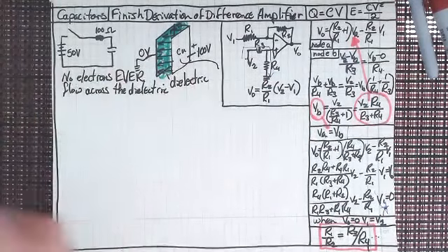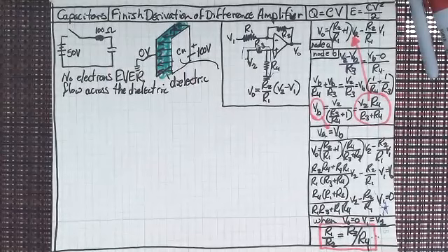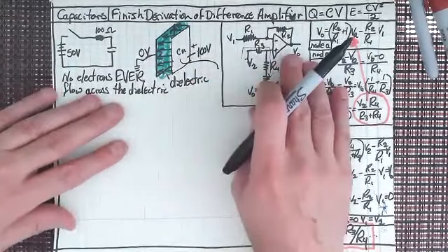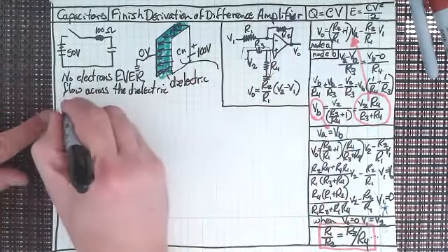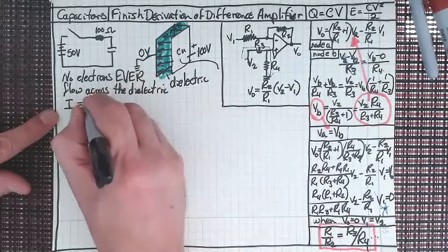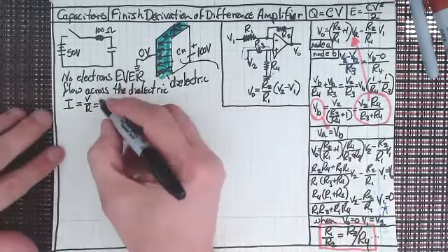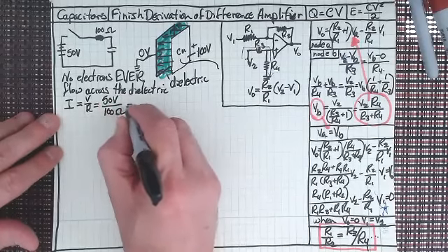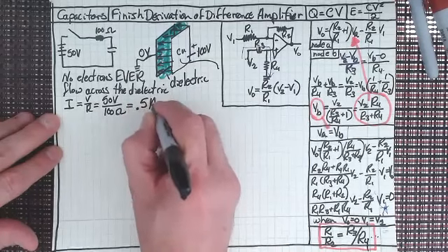There's probably some electrical engineers that do not really understand the physics behind a capacitor, and that we're storing energy in the electric field, right? So you're probably saying, well, when he throws that switch, what's the current going to look like? What is our maximum current? I don't even have to write Ohm's law anymore, do I? It is going to be V over R. So our maximum current is going to be 50 volts divided by 100 ohms. That's 0.5 amps, isn't it?